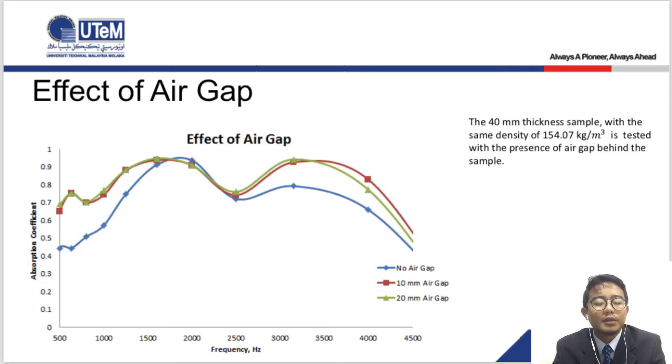frequency of 500 Hz. The sound energy inside the impedance tube passes through the fibers and directly to the wall and then circulates in the air gap before being reflected back to the fiber. The more space between the wall and the sample will contribute to more air particles vibrating and dissipating the sound energy.